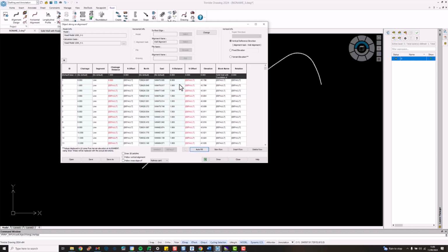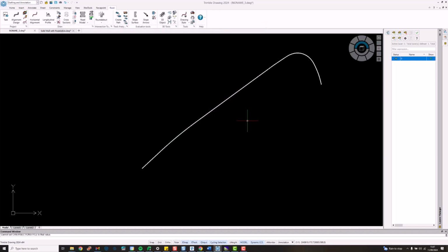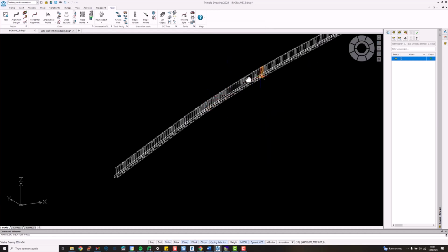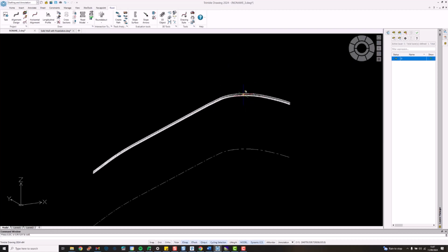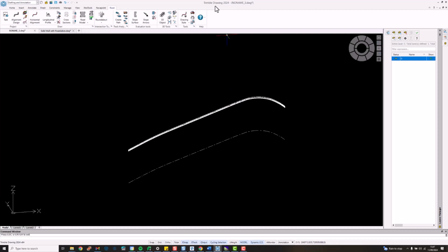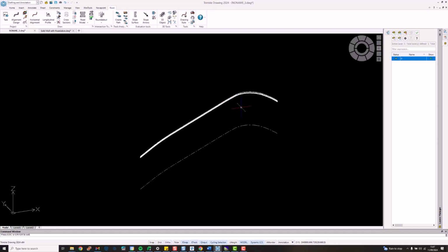Then I press OK. So it's auto-populated that, and if we scroll down, we can see there's changes in elevation here, as well as the northings and eastings as we go across. If we go all the way down, we can see everything seems good. So from here, I'll press Draw, and in my case, I don't want to save the table. Now, if I just get a 3D view of this, I can see that it has created our walls along there. Perfect. Now, all we need to do is save this DWG and import it to Quadri.